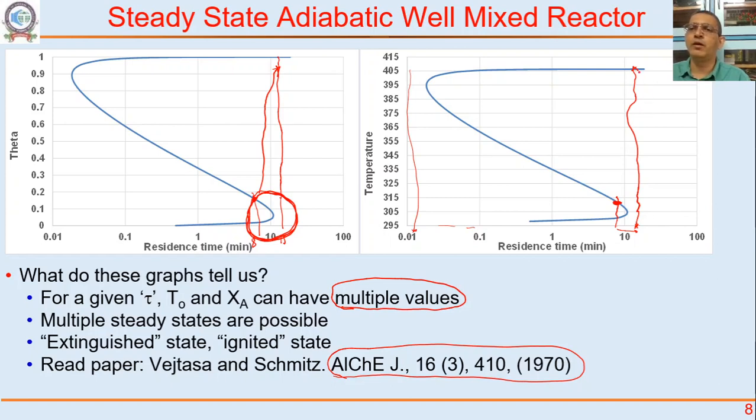Or same way, if you are reducing residence time, either pump flow rate has gone up, or you deliberately want less reactions, so you are trying to reduce the residence time by increasing the flow rate and things like that. Your conversion will drop from 99% to something like 5%, 10%.